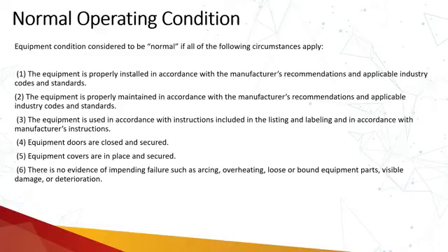This is one of the manufacturer recommendations about the operation of those electrical equipment, because during live operation, or operating at load or unload, it might cause arcing, which might quickly degrade the electrical equipment and shorten the life of the electrical installation itself.